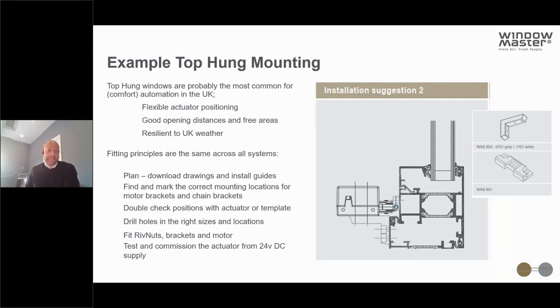So it's a case of planning, downloading drawings and the installation guides, getting a good handle of what's needed, finding and marking the correct mounting locations, double checking, of course, those positions with the actuator or a template, drilling the holes, fitting the riv nuts, brackets and the motors, and then testing and commissioning the actuators, that can often be done from a 24-volt DC power supply.